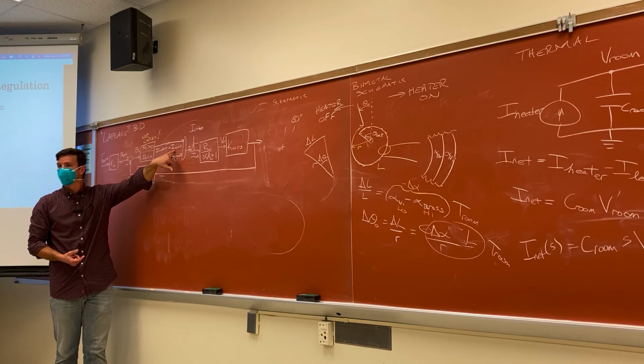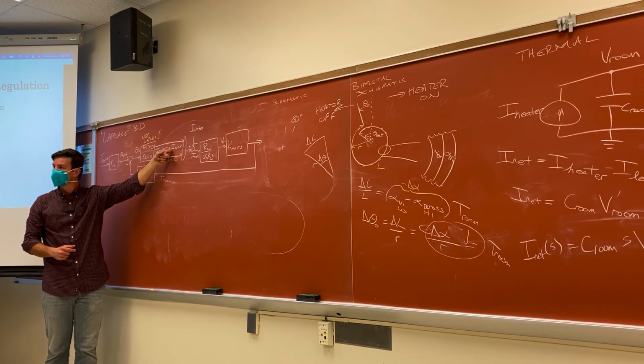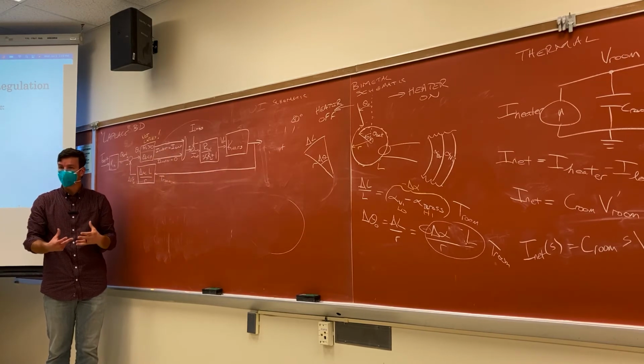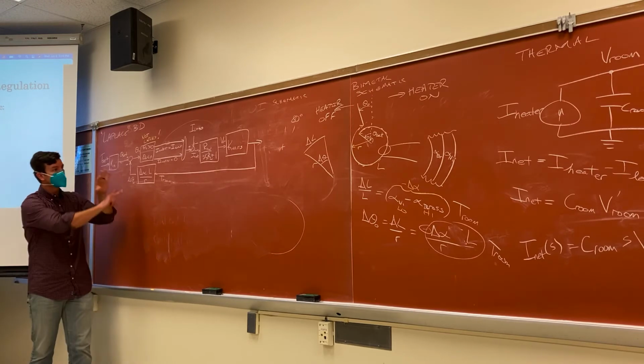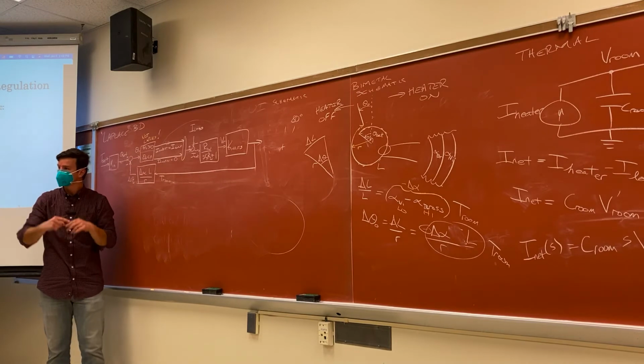Sizing the heater changes nothing except for the size of this signal, which is a little surprising if you think about it. If you have a 500 watt heater versus a 5,000 watt heater, nothing else changes except for the magnitude of this step. Yeah?